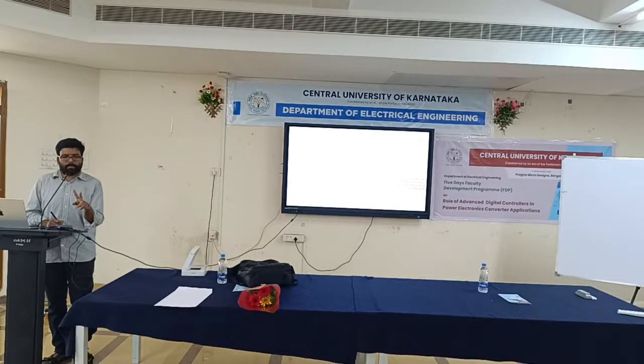If you want to satisfy position or speed requirement, as a controller, what is the target parameter? Torque. By controlling the torque, first you need to identify the required amount of position or speed from the customer's point of view. You have to get the information. Once you know the information, as a controller, it is not a big deal to control the torque. By controlling the torque, we can control the speed as well as position.